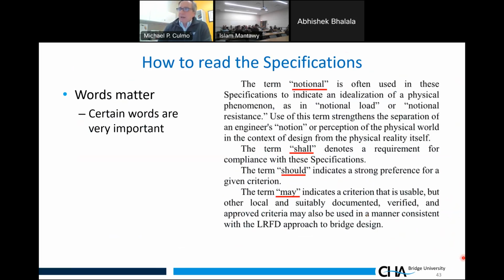State DOT bridge manuals typically define the shoulds and the mays. They'll actually say that in this particular criteria, may means shall. You have to do it. When in doubt, make should and may shalls, and you're going to be fine. You don't have to make a decision, but it's very infrequent that we actually ignore a provision just because it says may. By and large, we equate shoulds and mays to shalls in most cases.